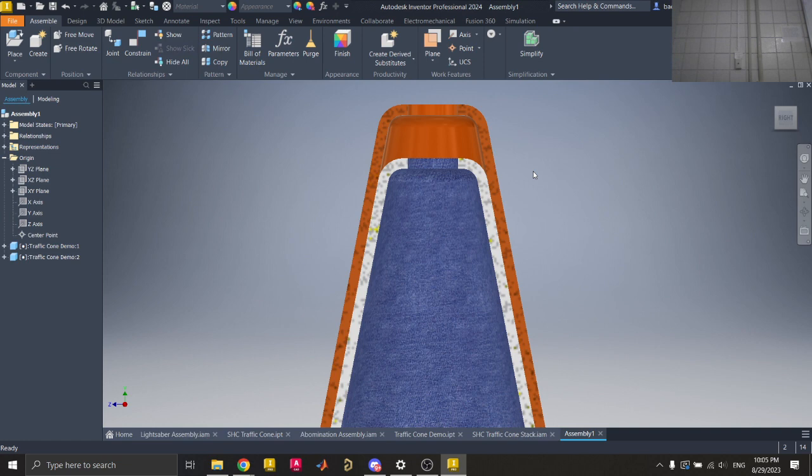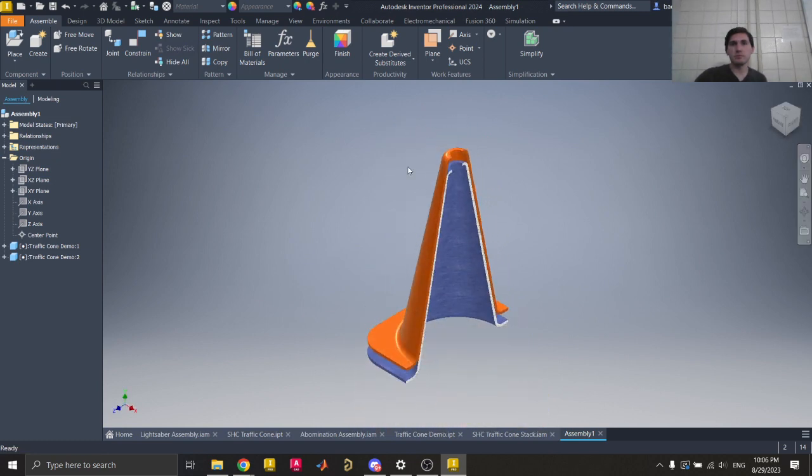So you'll go to View, and then you can just pick one of the planes. You can pick any of them really, and then just hit the little check mark, and then you can go out. So now you can kind of see on the inside, and then you'll just make a tangent constraint between the inner and the outer surfaces of the cone. So now we have that.